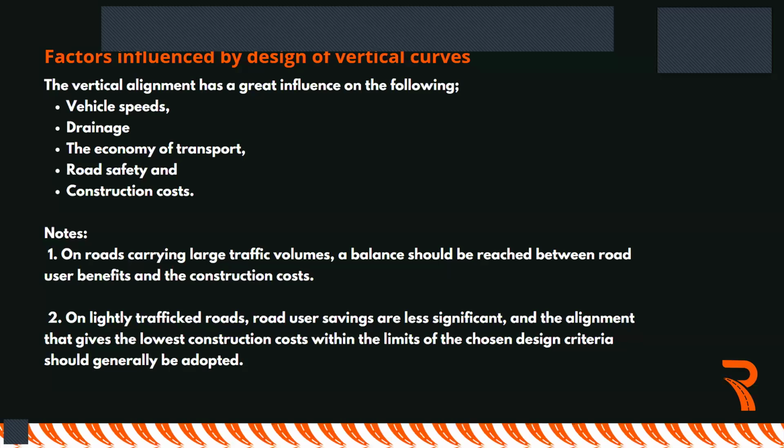That then explains why you will always notice very heavy earthwork along major roads. Along roads that have very high traffic volume and capacity, the government invests a lot in major earthworks to make sure that the slope is below 4%.